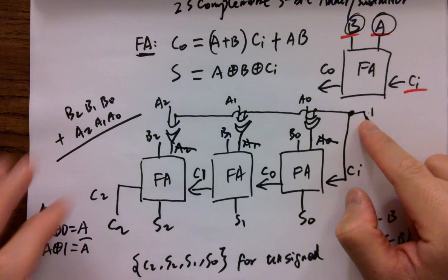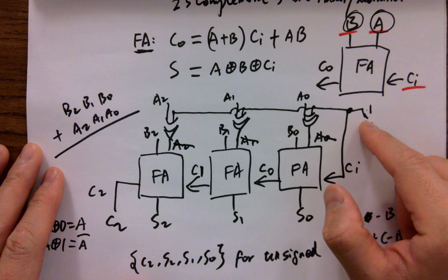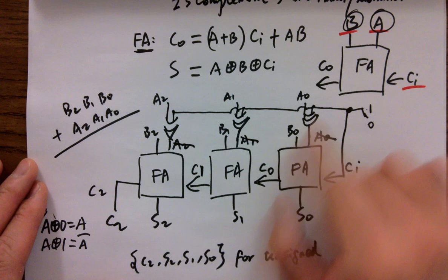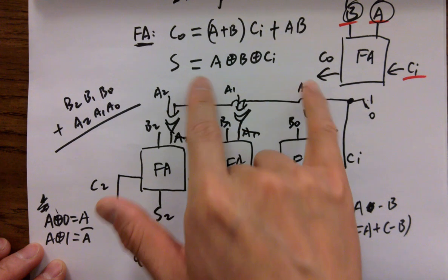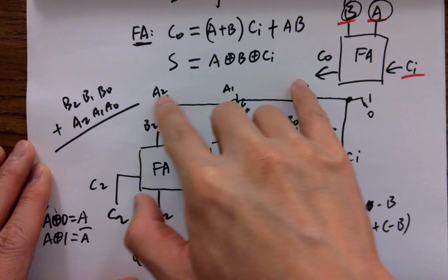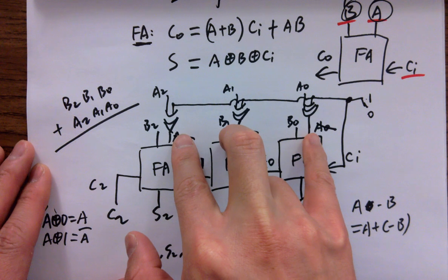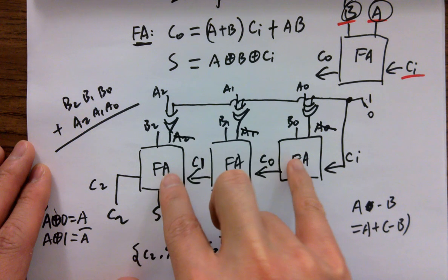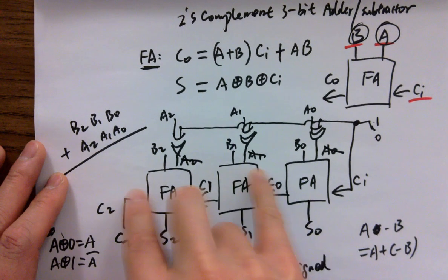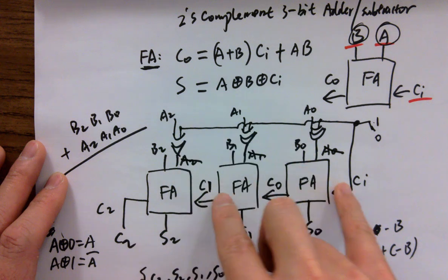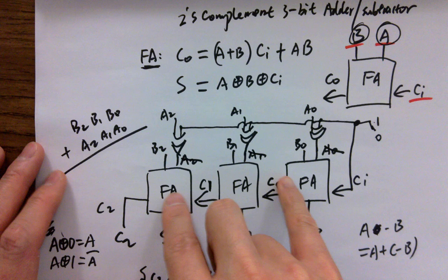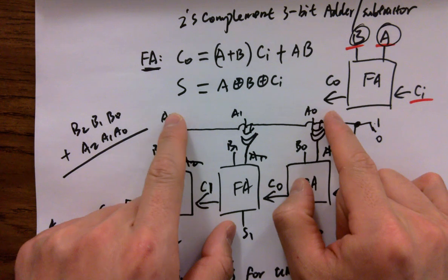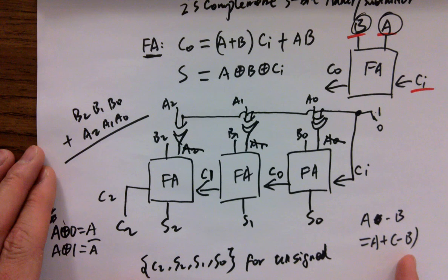So if you switch it to 0, what's going to happen? If you switch this to 0, feeding 0 to one of the inputs of the XOR gates, A XOR 0 is still A, so it's not changing it. A will be passed through the XOR gates, and you are still getting B adding to A, because these FAs are doing the adding operation but not subtraction. They don't know which kind of operation needs to be done. All these FAs are only doing additions, because that's what the internal structure determines. So you have to convert them into the negative counterpart in order to do a subtraction operation.